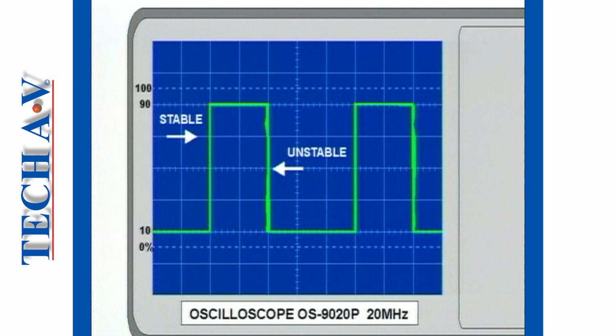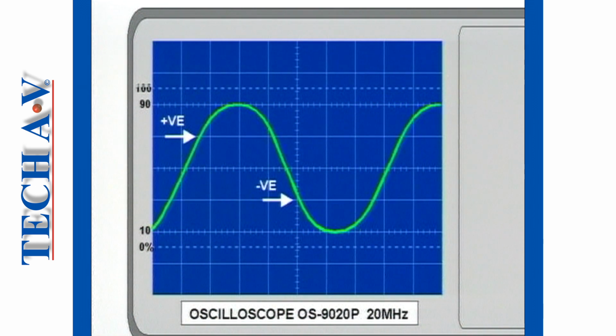As a rule, always choose the signal with the steepest slope and the least amount of jitter for reliable triggering. For slow rising waveforms, we use the midpoint, as this area is usually the cleanest part of the transition.